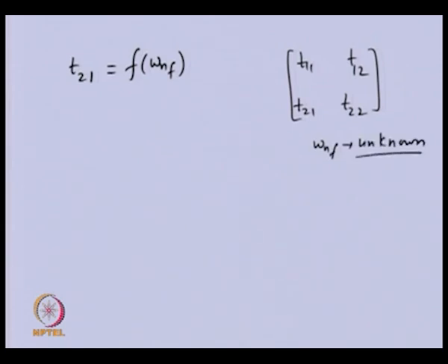So unless we know this, numerically we cannot multiply the point matrix and field matrix. So for that purpose, when we solve the natural frequency using a numerical technique, we assume some initial guess of the natural frequency, let us say a very small value, 0.01 radians per second. Once we assume this, we can see whether this function, the frequency equation, is satisfied, because this is the initial guess.